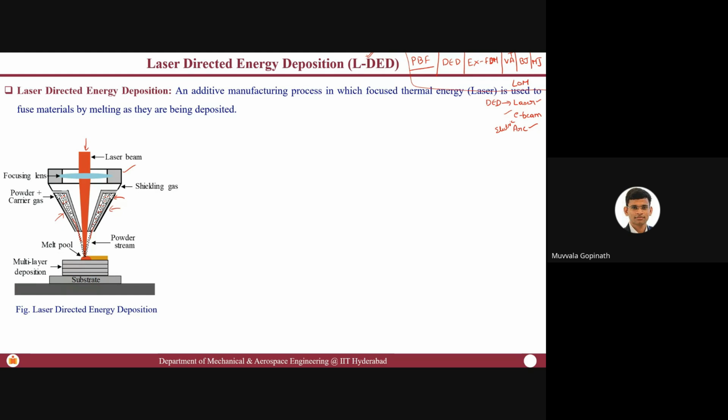And then as the laser beam moves in this direction, the molten pool formed by the laser on the substrate, plus the powder which entered, will form a bead. And then you have something called overlapping tracks. Overlapping tracks, if you are using them, is typically called a laser cladding process. Combined with overlapping layers, it will result in additive manufacturing.